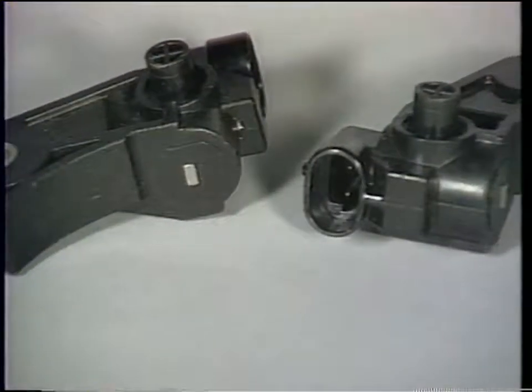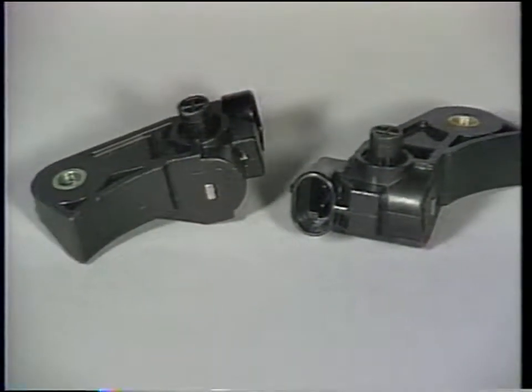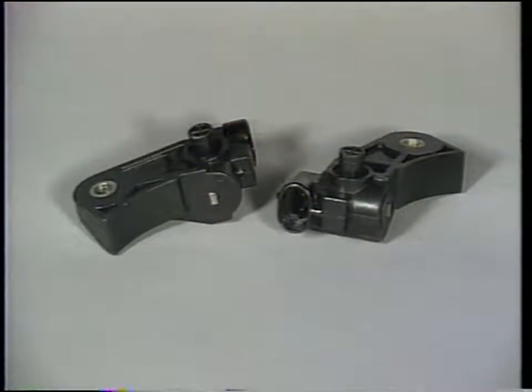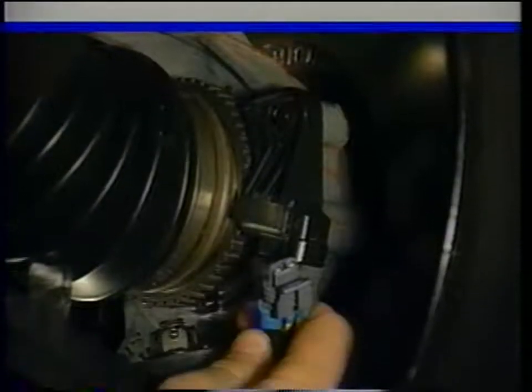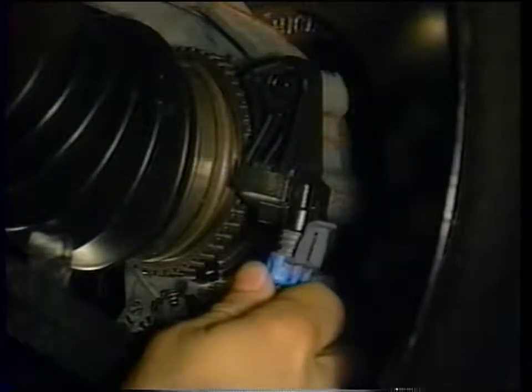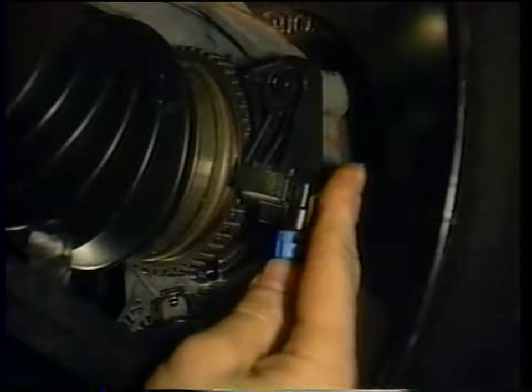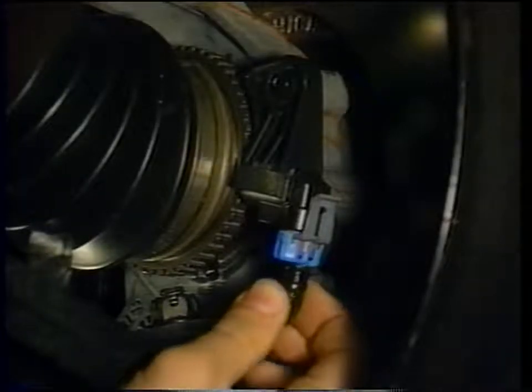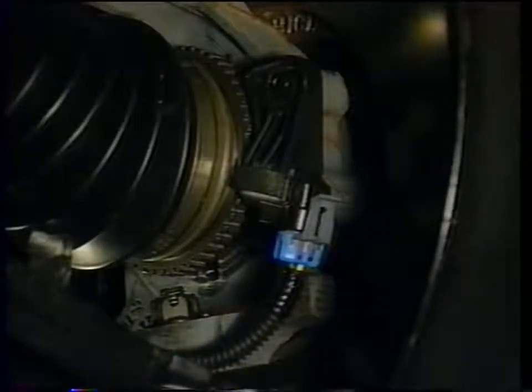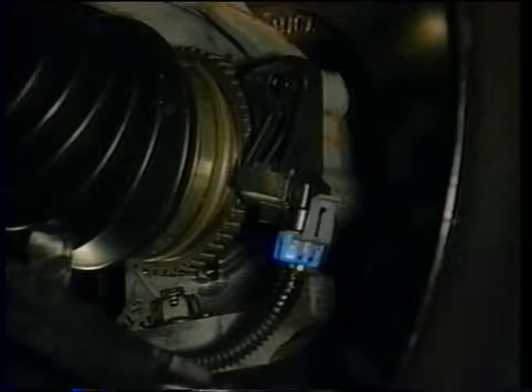An unusual feature about the front wheel speed sensors on the Delco 6 system is that they're made of plastic rather than stainless steel, as is used in most other ABS applications. This lowers the manufacturing cost of the system, but also makes the sensors a bit more vulnerable to damage by careless handling. Never pound on one of these sensors or attempt to force it into place. The sensor should slide right in. If it doesn't, check for obstructions. The plastic sensors do not need to be coated with a corrosion-inhibiting lubricant prior to installation.